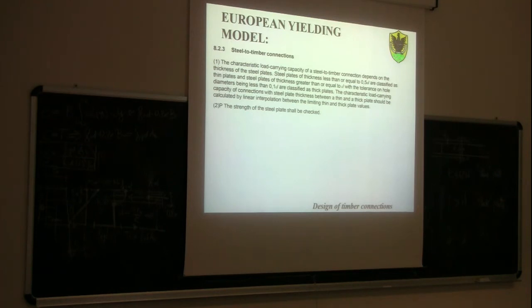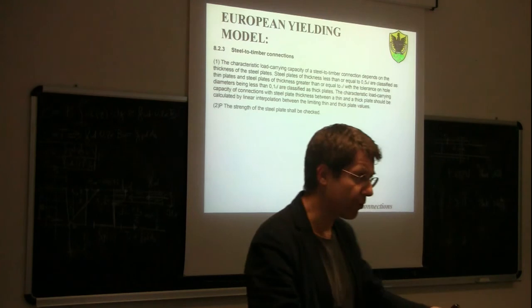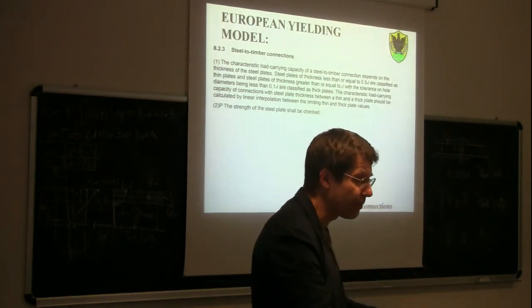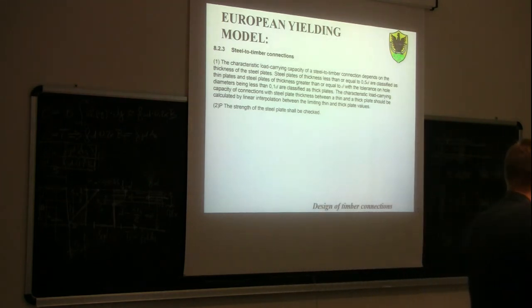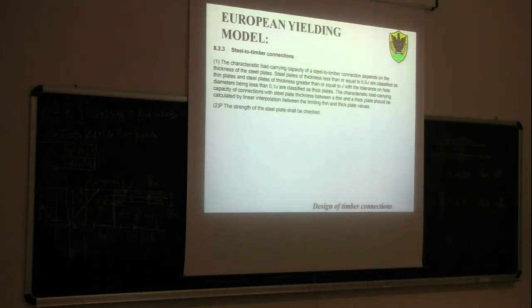Now, another important thing, the tolerance on hole diameter, less than 0.1d. What is the tolerance of the hole diameter? Also in steel structures, you can't have the diameter of the hole exactly the same as the diameter of the bolt, because you always have some small error in building your structure.